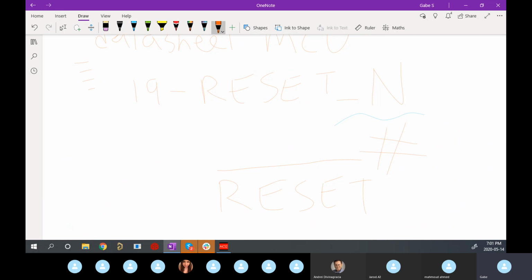Well, no, because the reset pin is active low, which you would have known if you had written this down. When the reset pin is low, it's active in what it needs to do, which is reset the microcontroller. When that pin goes low, it's being reset. Whenever that pin is high, we're chilling, everyone's fine, and there's no need to reset anything.